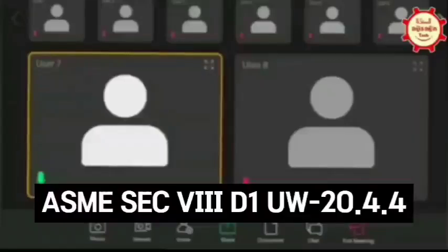Yes. But if a client specification mentions that you have to do a pull-out test, tie a mock-up, and now my FR value is coming less than 0.9, then what do I have to do? Now my mock-up is failing. My FR value is coming 0.7. I can't do anything. What can I do now?